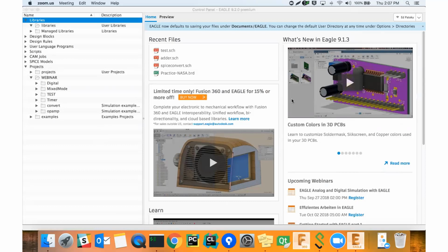So let's start. What is simulation? Basically, simulation is a way for you to simulate your circuit with a SPICE-based simulator, which is what we do in Eagle, a way for you to pre-calculate how your circuit is going to act. As we posted in the summary for the webinar, it may be something as simple as verifying the current through a diode, or it may be an advanced sensitive circuit design, maybe an amplifier, a filter, whatever it is. Something very carefully done by hand, and maybe you want to verify it before you actually go and build it.